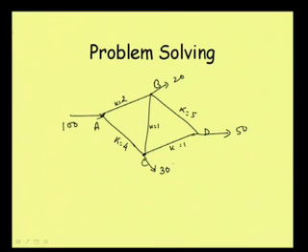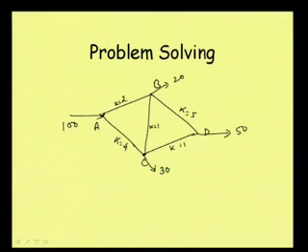Now let us assume the first approximation. As this k value is smaller, that means head loss k Q to the power n, or rather when the k value is smaller, we can consider that roughness is less, or the total resistance offered is less, or head loss will be less in this direction. So for a smaller k value, we can always consider the higher discharge. Let us first assume that 100 will be divided like this: here it will be going 70 and here it is 30.